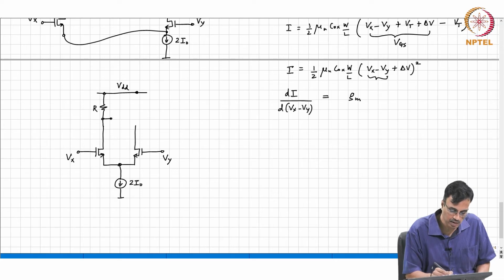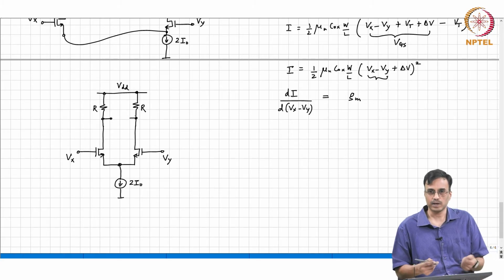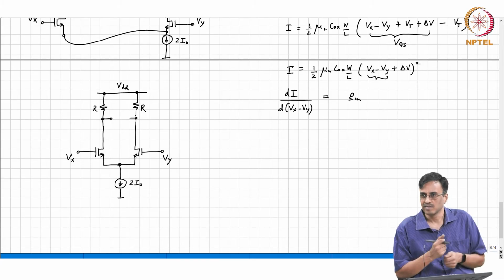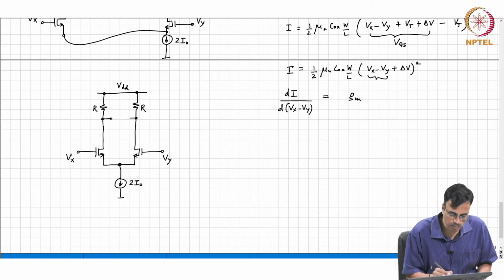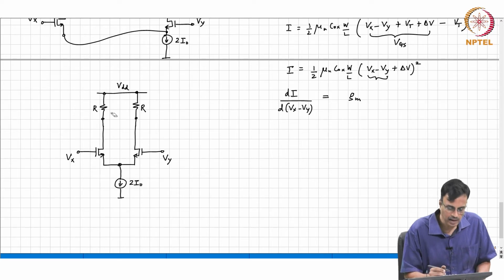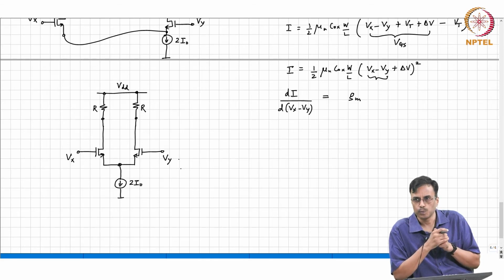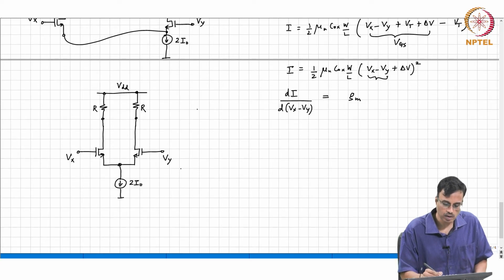So, basically, this whole situation is symmetric with respect to whether you want to find Vx minus Vy times A or Vy minus Vx times A. So, if you put a resistor in both drains, then you will have the same incremental output with opposite sign depending on which drain you tap, okay. So, this is the so called differential pair or differential amplifier.